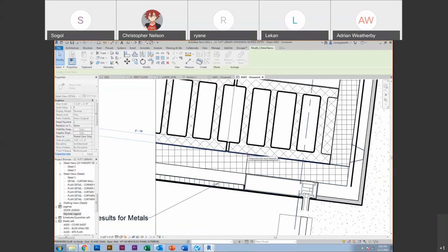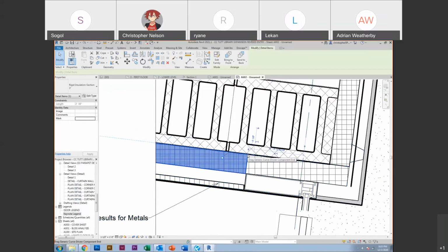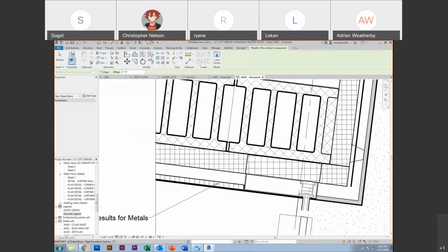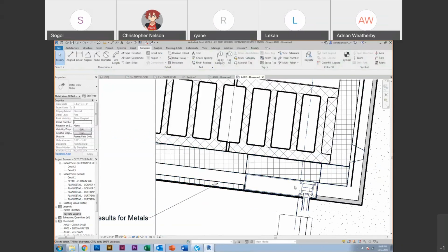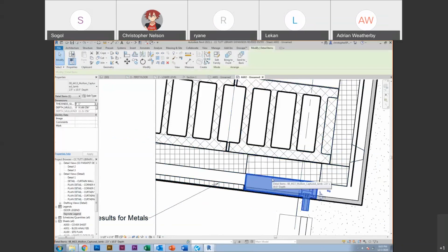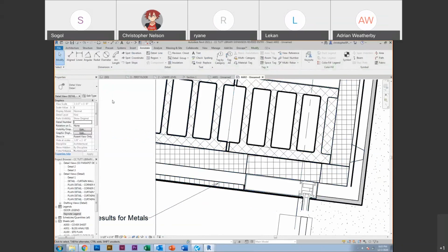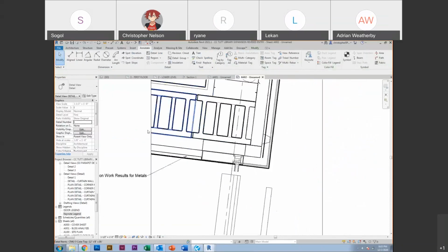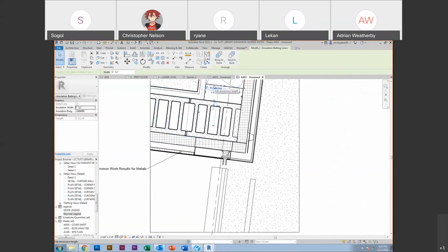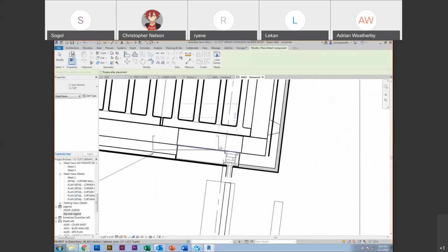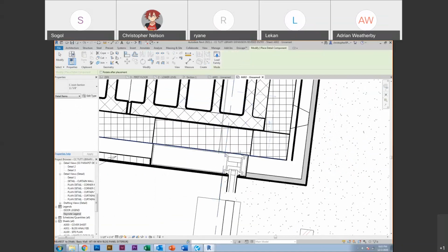I know there's going to be a few issues as far as kind of like thermal breaks and stuff like that. But I think I'd probably wind up putting that thermal stuff on my mullion. My mullion would have a thermal break on it. And then the gap between my CMU and this mullion would be blocking, whether that's like a stud or most cases it's going to be a piece of wood that they're going to kind of shove between it.